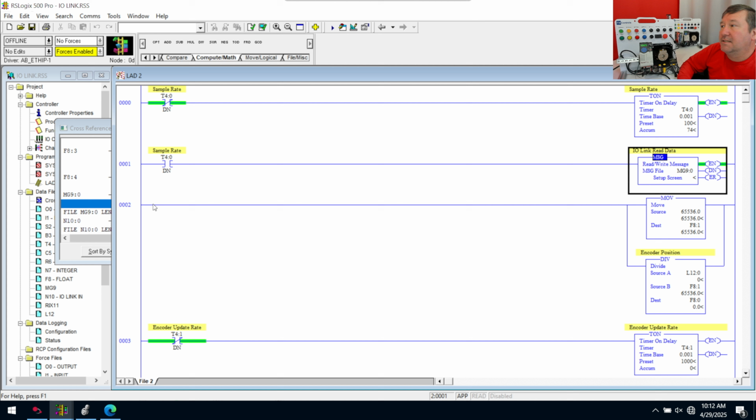And arbitrarily, I'm just going to say that our PowerFlex program is the one that we are going to keep, just like it is. So we're going to highlight rung 0, go down and highlight rung 5, right-click, and copy all the rungs out of that program. We're going to go over to here, make sure we're in our PowerFlex routine, right-click, paste. You're going to get some warnings about some collisions. It should only be S:1/15. We're going to hit replace. This program we're going to run just like it is.